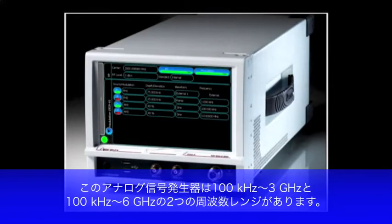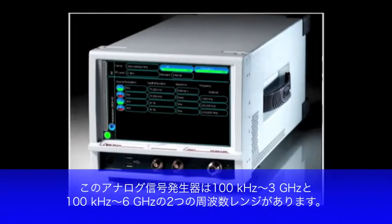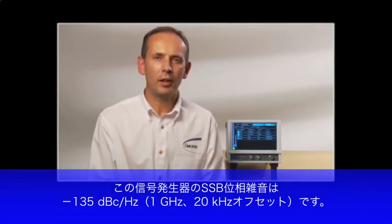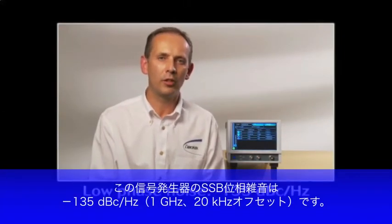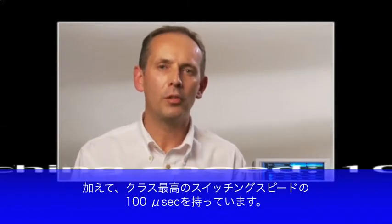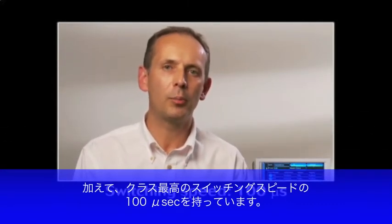And today I would like to introduce to you our S-Series SGA signal generator. This analog signal generator is available in two frequency ranges of 100 kHz to 3 GHz or 100 kHz to 6 GHz. This analog signal generator has outstanding phase noise of -135 dBc per Hertz at a 1 GHz carrier frequency, 20 kHz offset. Combined with this low phase noise performance is a class-leading frequency switching speed of as low